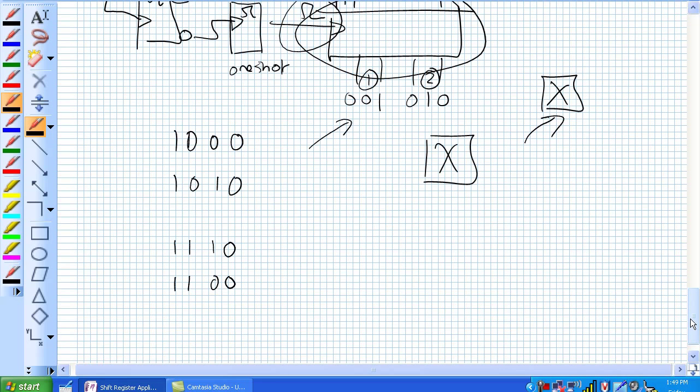You're like, let's just put in all 4 zeros, and you get out 0, 1, 0, 0. What's going on there? For some reason, you've got a short to VCC on that bit position right there. Regardless of what you put in there, you're constantly loading a 1.